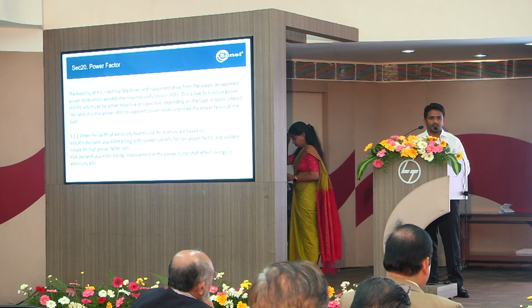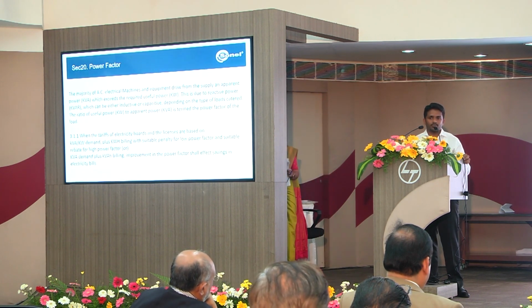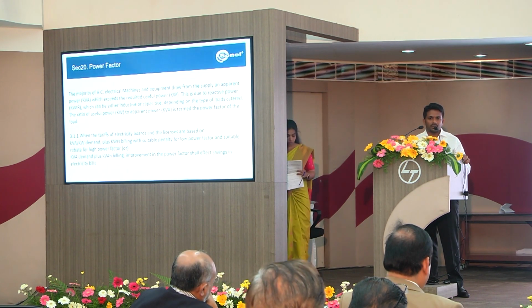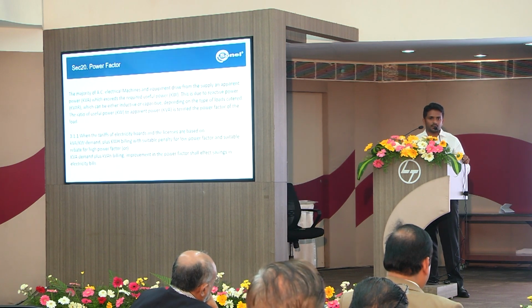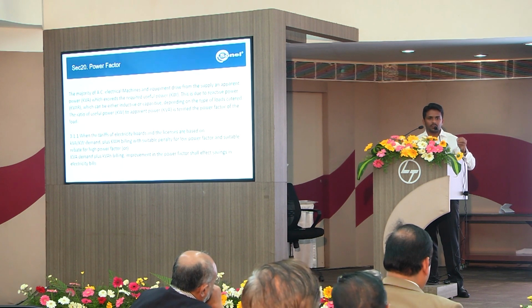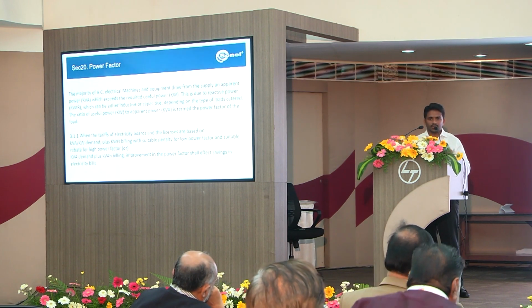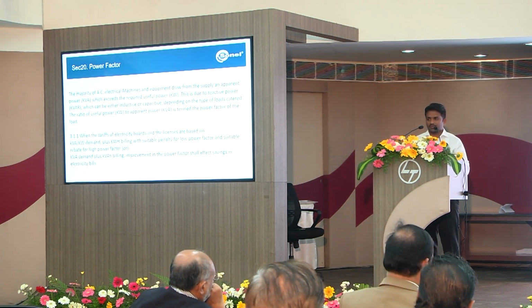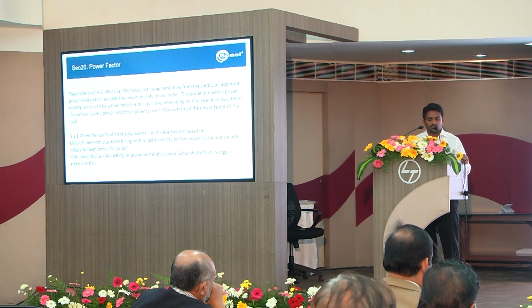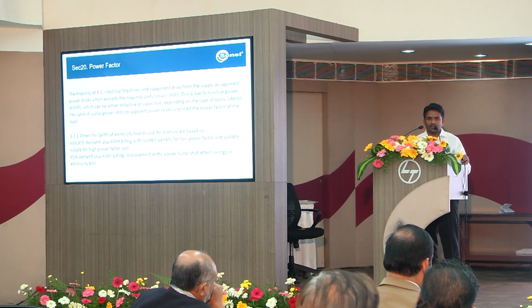I put it into the second line. It's an example of Tamil Nadu, for example. We, not being in the kVAH billing like other states, will have to maintain our power factor. If you don't maintain your power factor, there could be a possible penalty or a rebate that varies from state to state. If you are in a kVAH state, it is understood that if you maintain your power factor, you are going to have an electricity saving.